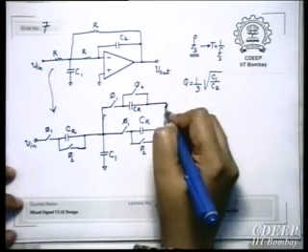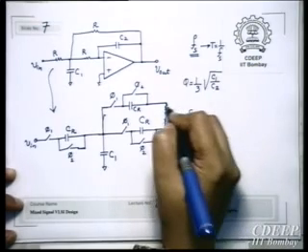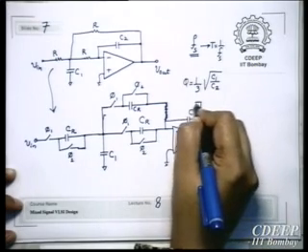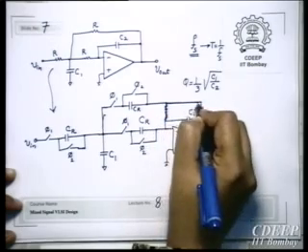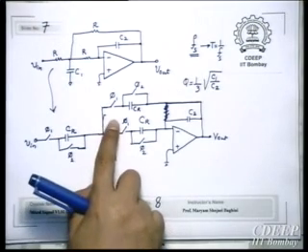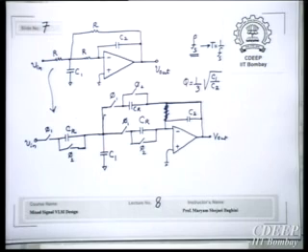Yes, correct. Sometimes it happens, we can even simplify more. The reason is because some of these switches come in such a way that they operate simultaneously. Therefore, you can remove them and just connect them. See whether something is here or not. Can you simplify? Because this is helpful, you can reduce the number of switches.